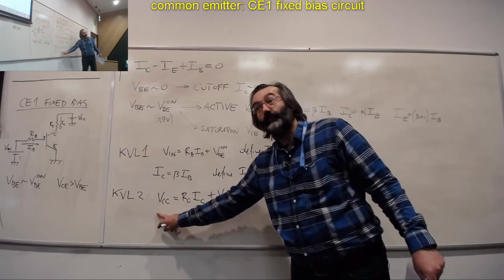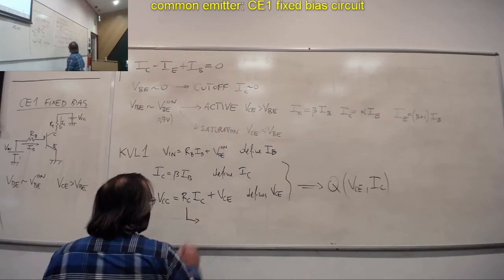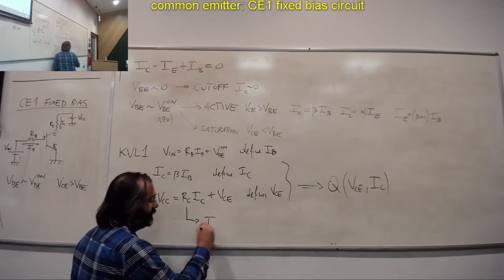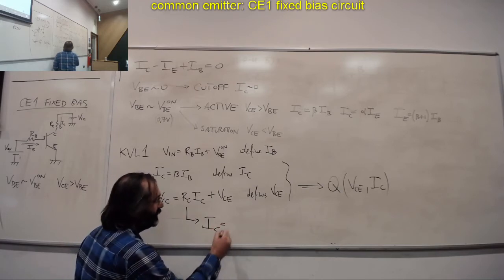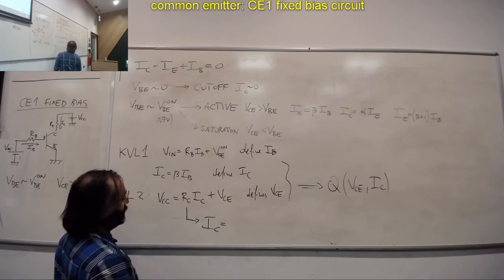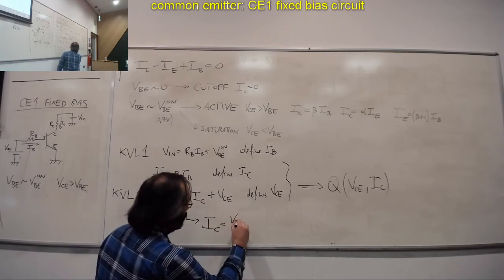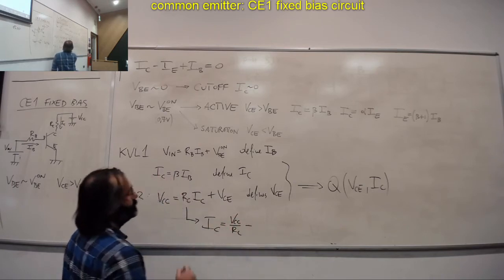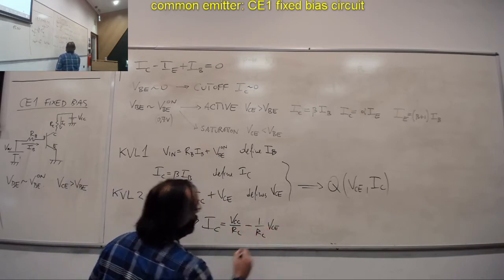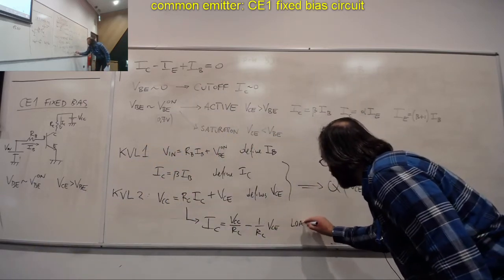We've called this equation the load line, or maybe what I will write now, by explicitly writing the dependent variable on the output characteristic, IC, in terms of the independent one, VC. So you need to invert this relation and write IC equal VCC over RC minus 1 over RC VC. You see, this is what we used to call the load line, as we've seen with the diodes, with the PN junction.